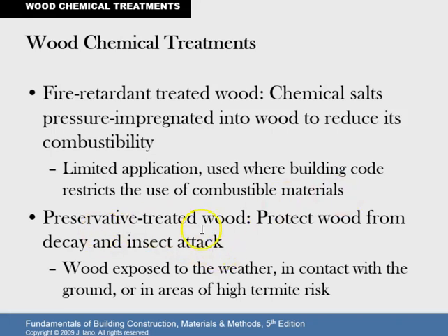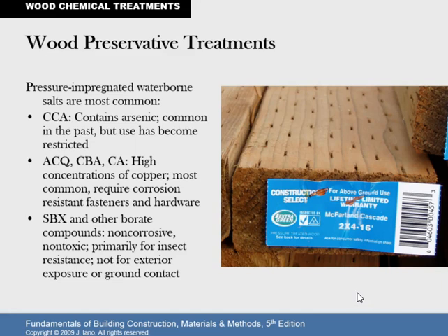However, preservative treated wood, or pressure treated wood, is much more popular. So this is any wood that's exposed to weather, in contact with the ground, or at high termite risk, or in contact with concrete would be pressure treated. Okay, so this is getting into the finer points of preservatives, and we are going to skip over that.